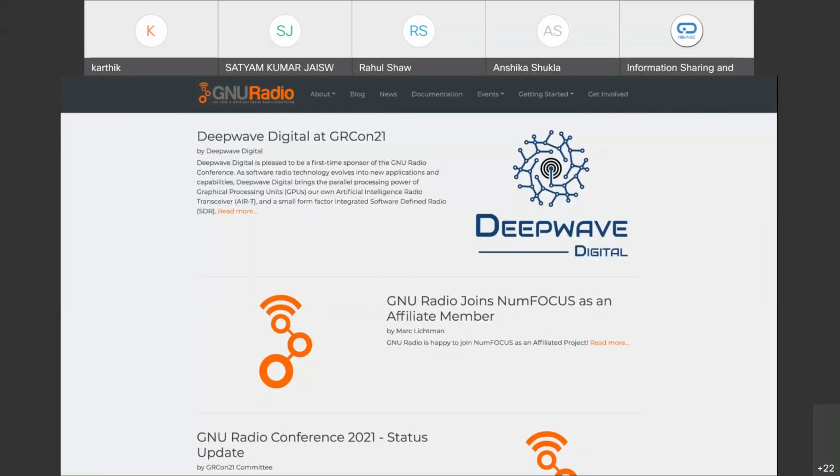So you can write a program in GNU Radio where you take that text file, convert it into binary, or Morse code or whatever it is, and then apply the proper encoding formats to transmit that signal, so that anybody with a receiving SDR on the other end will be able to receive all of this data, and if they're smart enough, they'll be able to figure it out on their own.